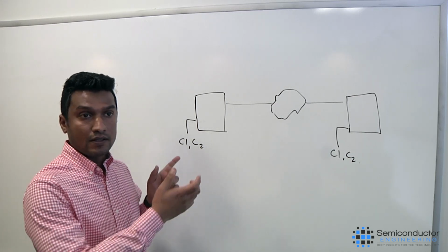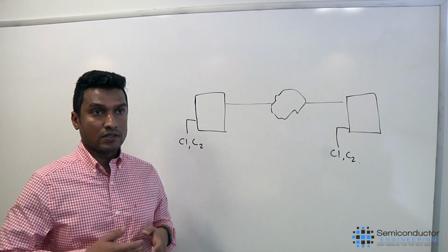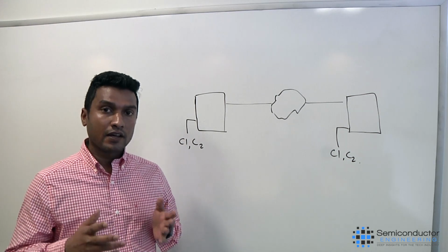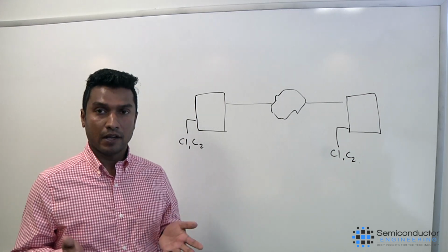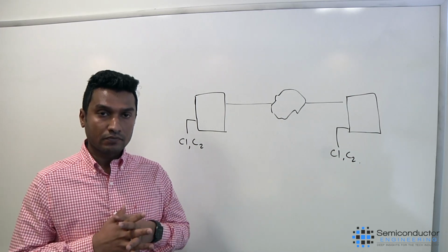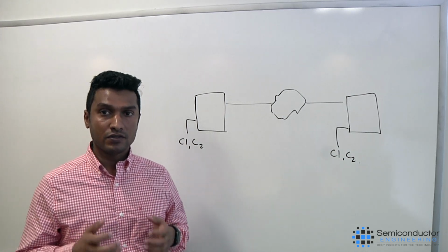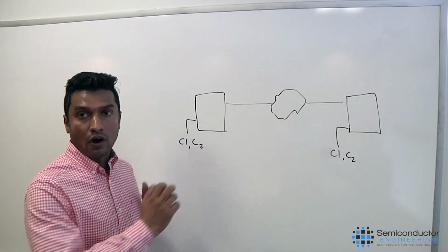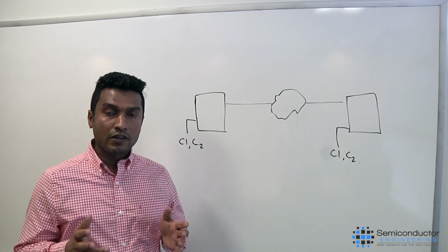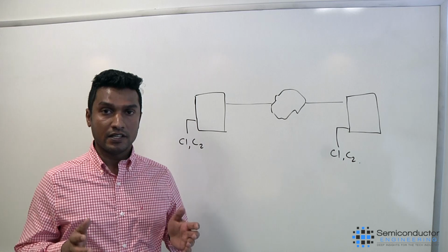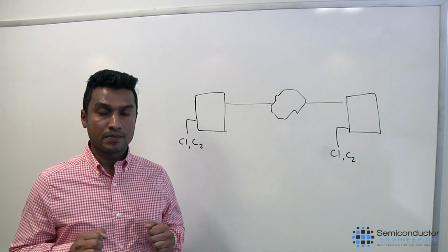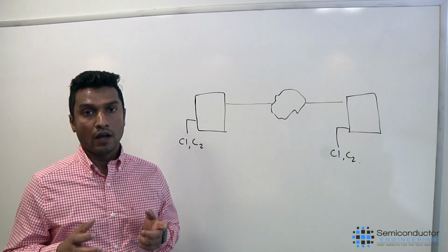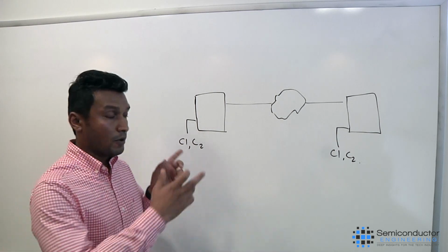So if somebody wants to get or filter out these crossings in the design, sometimes you will have to request this kind of feature from R&D. But if you are in a critical project with a critical timeline, you don't have time to waste. So what you can do is simply create a custom check using the Tcl capability that we have built in VC Spyglass to filter out all these crossings. We have a powerful Tcl command called get_cdc_paths, which is inbuilt in VC Spyglass. Once you query that command, it will give you a collection of information about this crossing.